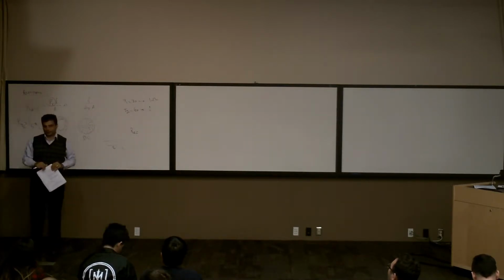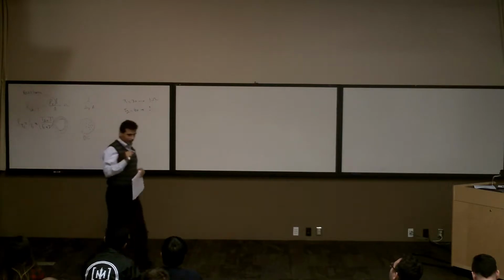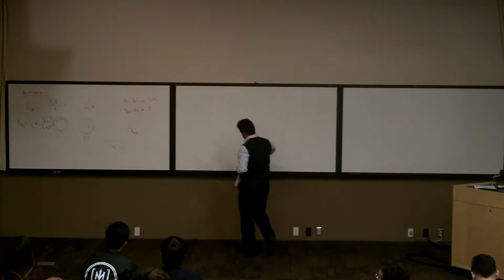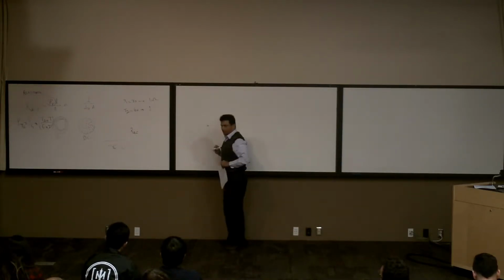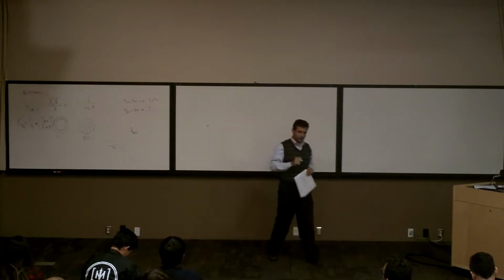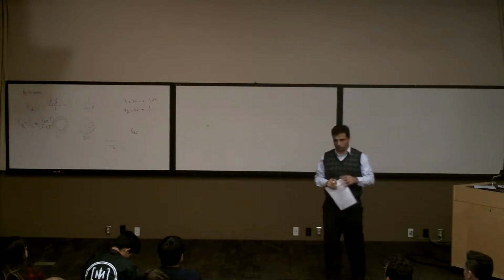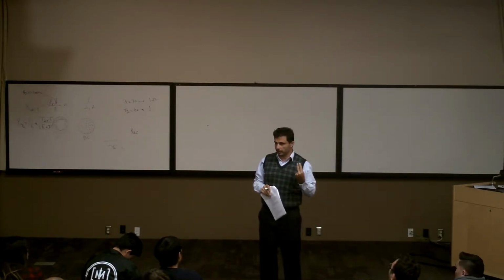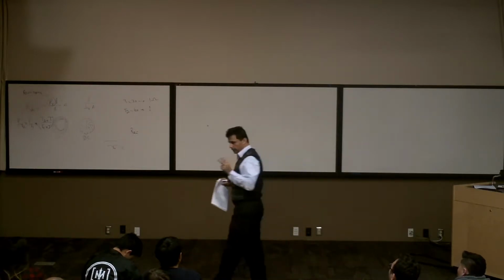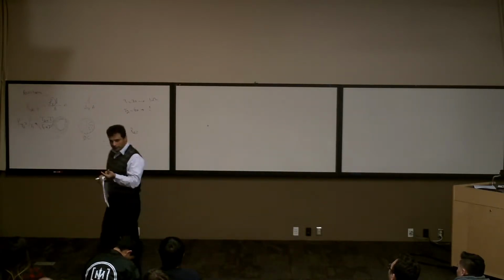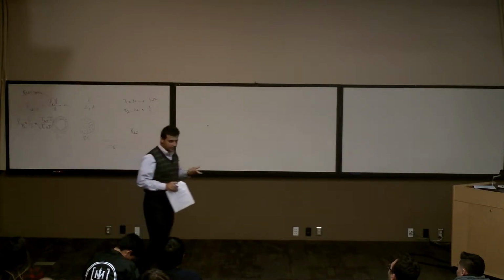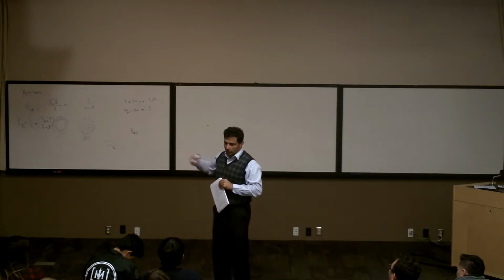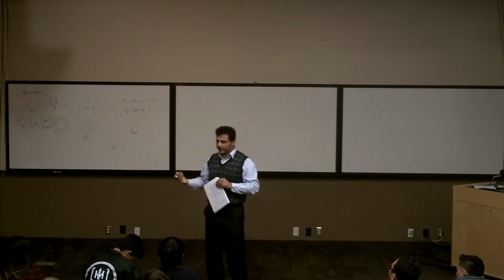If you look at all the transmission lines, I cannot draw the picture here, but the wires are like this. We have different materials for the conductor. We can use copper, we have seen copper everywhere. We can use aluminum. You haven't seen that much aluminum, but in transmission lines there is aluminum, very widely. And we have silver, and we have different materials. Among all of these, silver is the best conductivity-wise. It has the minimum rho. So the minimum rho, the better, right? So basically, it has less resistance.